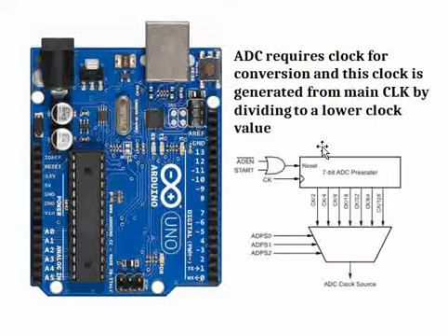And then in a microcontroller, for any interface internally, we mentioned that the functionality entirely depends on the clock, because these are all digital, right? So it entirely works based on the clock input. So ADC also requires a clock, but this clock is not a clock frequency equivalent to the system clock of the Arduino Uno.